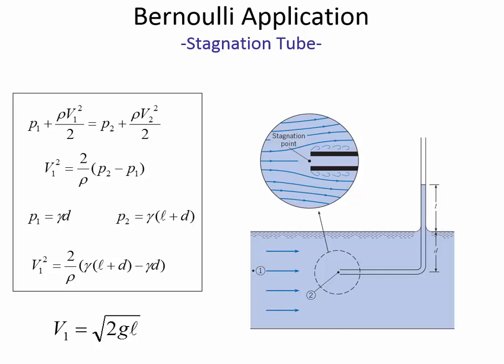There's even ways of putting a loop through the water and then measuring the magnetic effect of the fluid that's passing through the loop. It's turned into an electrical current. So there's lots of ways to measure flow, but that's the long answer to your question. How much error will there be? It depends on the shape of that opening, and it could be made to be accurate enough. Within 10% would be a reasonable assumption.